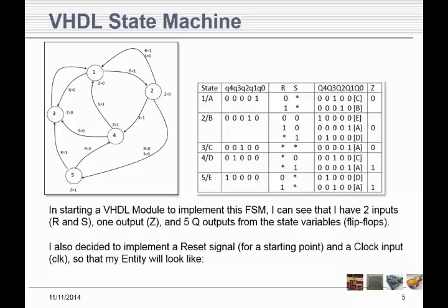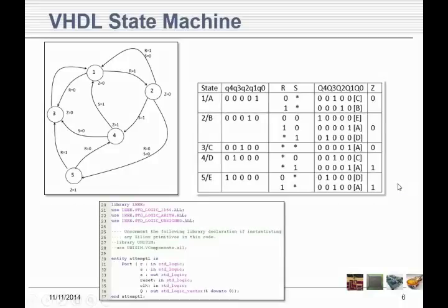But if you needed a clock, and there was a signal out there named something that could be interpreted as clock, it wouldn't put one in there for you. So I would always have someplace a copy, and it'll be in this presentation when I'm done with it, of the lines that need to be input in there to make sure that a clock works.